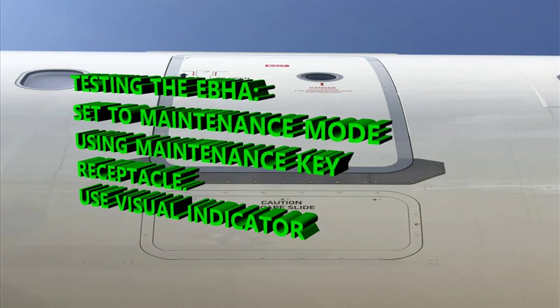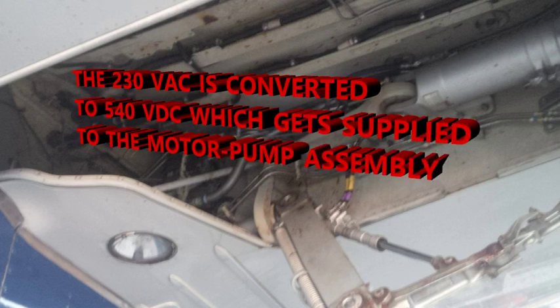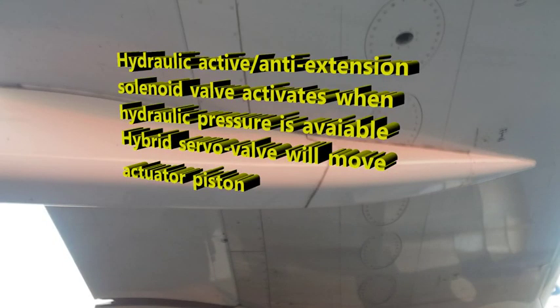Okay, now if you needed to test this particular actuator, there's a visual indicator that you can use, and you're testing all of this on the ground. If you have a loss of hydraulic pressure, then that voltage, that power is going to be changed to 540 VDC. It's kind of like, I was just thinking about other aircraft. If you take an A320 or Boeing 737, usually when we have things running, they're running on 110 volt AC, right? And then when there's an emergency, then it's going to be utilizing the 28 volt DC to run things.